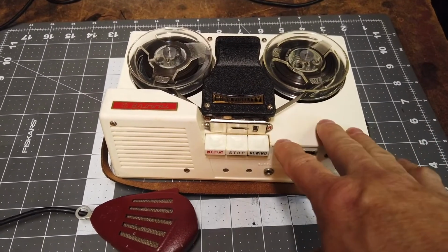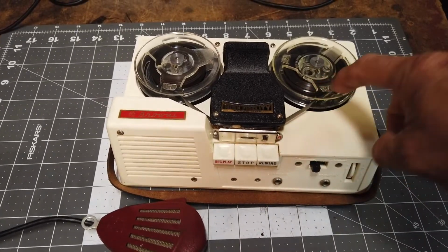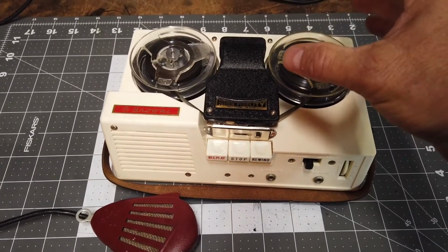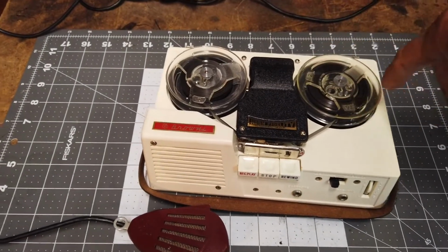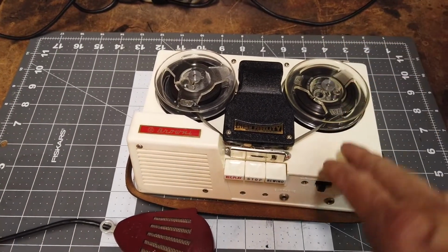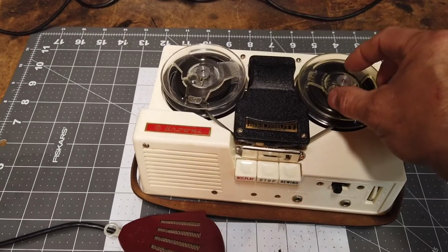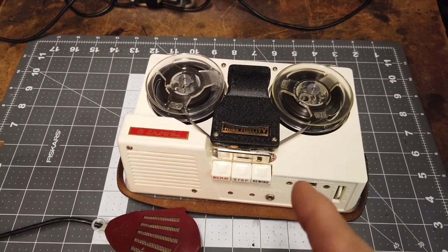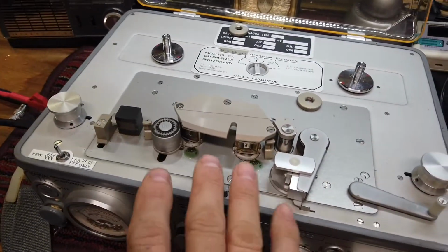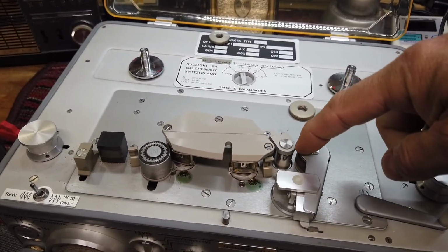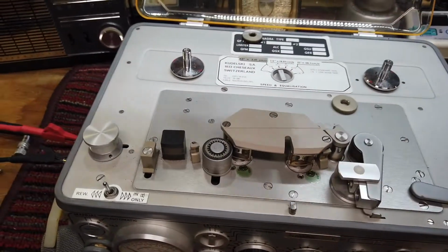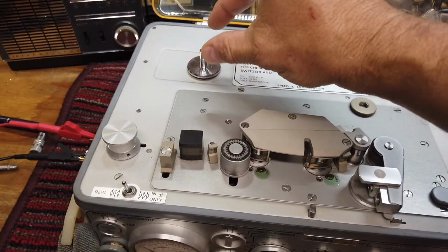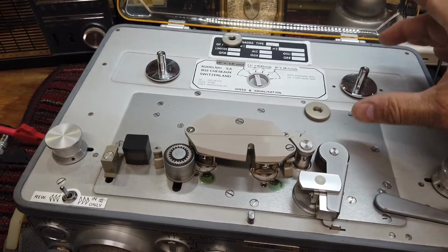Now remember, one of the challenges we have with these tape recorders is that with the rim drive, the playback speed increases as the tape builds up on the reel, so it's pulling more tape through per second than it originally is at the very beginning of the tape. So when I record tape on the Nagra, it's using a pinch roller, which provides constant tape speed no matter how far you are into the reel on either side.